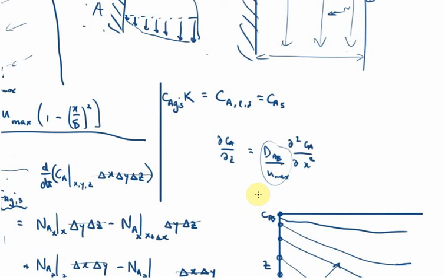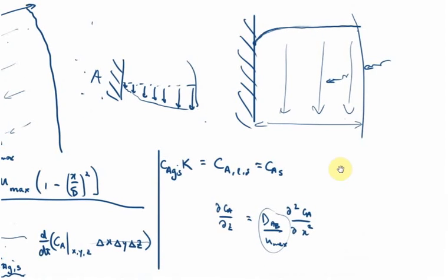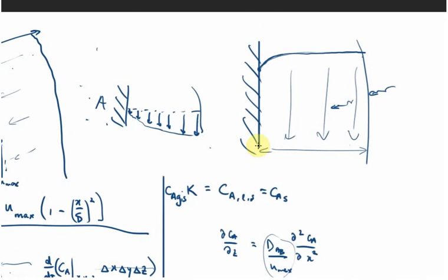And then the second one is, as we said, in the boundary condition, in terms of what's going on at the wall. So again, we said that this film might be considered thick enough that looking at just the wall, we can take this value as being far enough away from the surface that diffusion hasn't really reached there, that this film is falling fast enough that component A doesn't really have time to reach there.